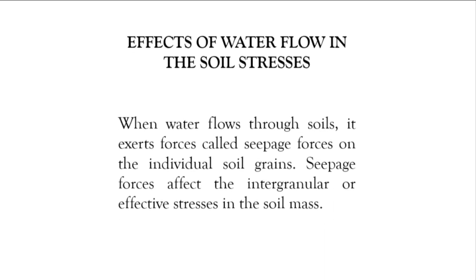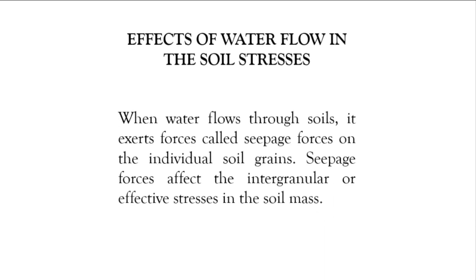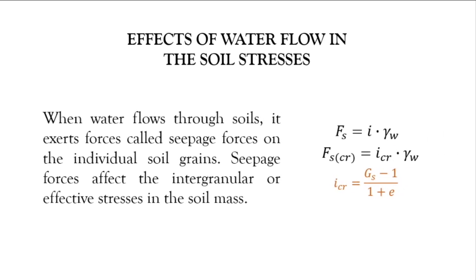So, when the water flows through soils, it exerts forces called the seepage forces on the individual soil grains, and the seepage forces affect the intergranular or the effective stress in the soil mass. So, ano yung seepage force? Seepage force can be calculated using the formula i, which is the hydraulic gradient, times the unit weight of water.